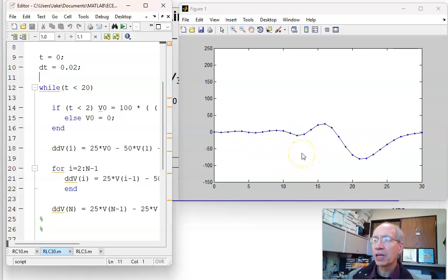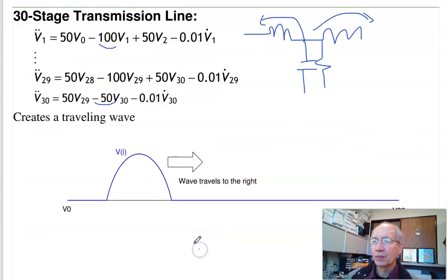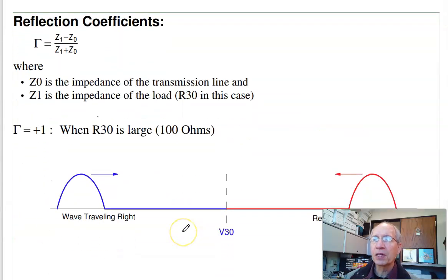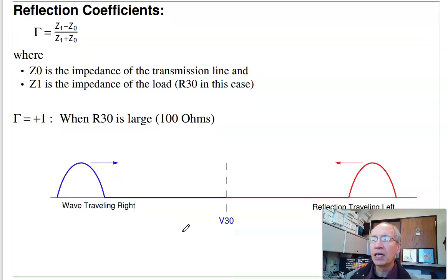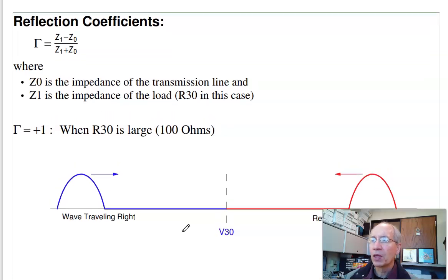So with wave equations, I get reflections. There's a thing called a reflection coefficient. It tells you how big that reflection is. Those reflections cause trouble. Those reflections are what's causing things like the bridge to sway in the breeze, the transmission lines to gallop. The energy is traveling down the line, and instead of dissipating, it just keeps bouncing back and forth. To calculate the reflection coefficient, there's a thing called gamma. That's the reflection coefficient. It's a function of the impedances.